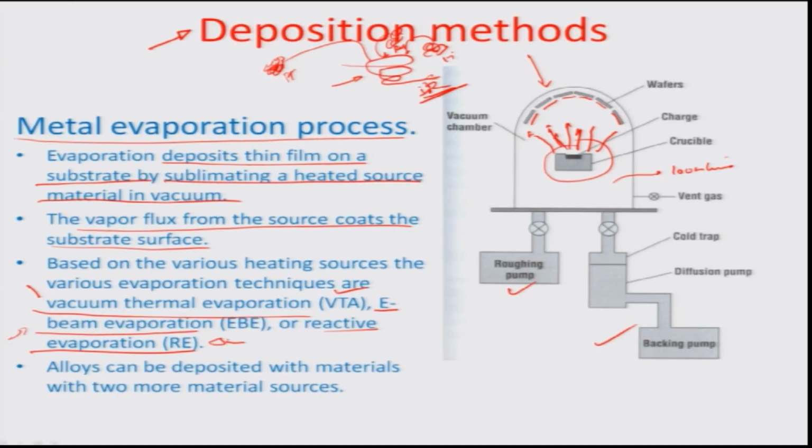If you have two or more metals working together, you can actually deposit an alloy as well, with a percentage constituent of both metals depending on the melting point. If one has a slightly higher melting point than the other, you could get a composition with a certain percentage of one over the other in the final alloy state of the material. So that is how you do one additive manufacturing process, that is, the deposition method.